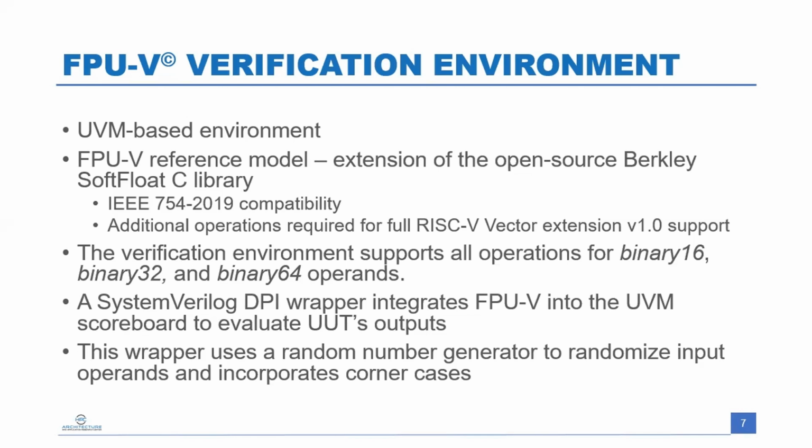So we have extended that library with certain operations and certain corner cases that were not there. We have also included some wrappers so that we can use it in UVM-based environments. For that, we also created random number generators that can test some of the cases and help us in evaluating the design and the operation.